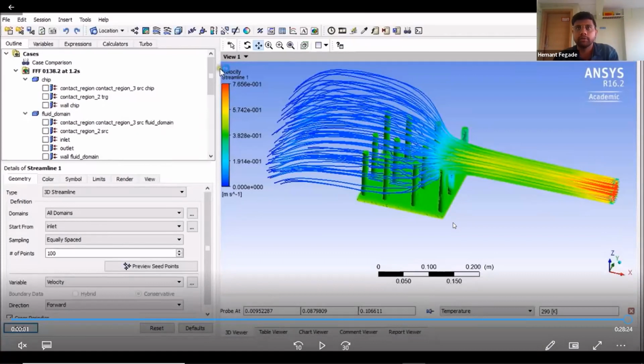You need to verify the temperature parameters with either a theoretical solution or an experimental solution in order to validate your simulation results, because this is just a tool. Its efficiency depends on the user's experience of the tool. Whatever input conditions you put in here, it doesn't necessarily mean that you are getting the accurate solution. You need to rectify these solutions with either theoretical data or experimental data to validate your results. So this is how simulation validations are done.